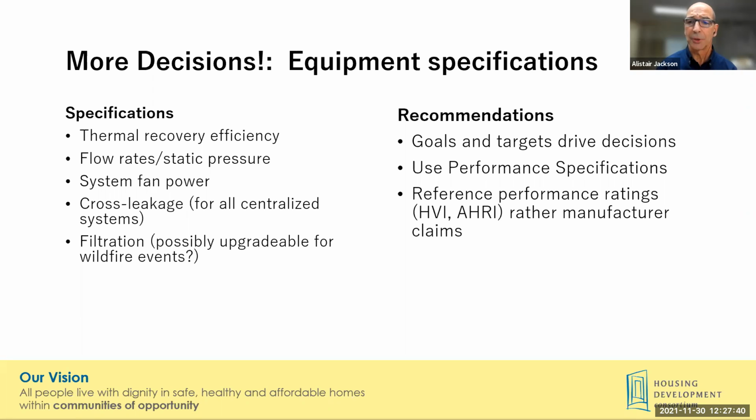By setting thorough performance specs for the equipment, you're empowering the subcontractors to propose the specified equipment or an alternative that's not going to compromise the overall performance of the system, rather than proposing an alternative that they see as equal but isn't necessarily so. And the other thing to remember is that manufacturer specifications may or may not be reliable. So looking for certifications and ratings by AHRI, HVI, and others may give some additional confidence in performance, but they do tend to limit options somewhat, and they can also be open to misunderstanding. So something to look out for.